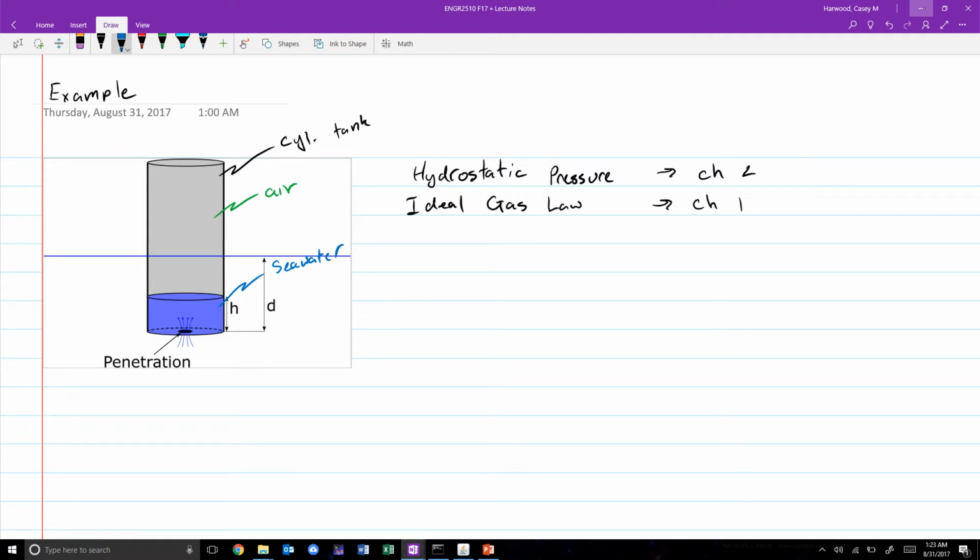So the way that this might initiate a dive, right, is by allowing air to escape through some valve at the top of the cylinder, which allows water to enter from the bottom, increasing the weight of the entire thing, making it negatively buoyant and causing it to sink.